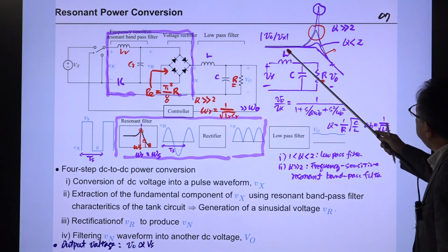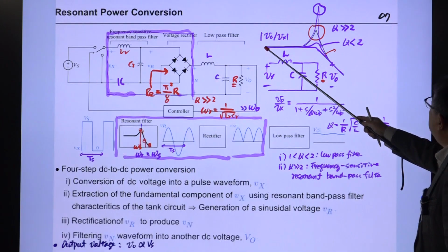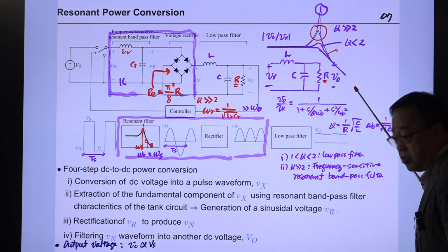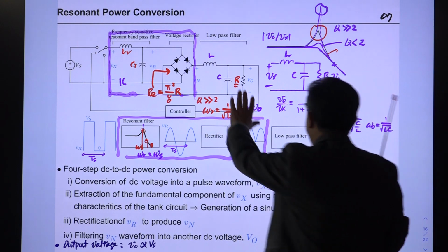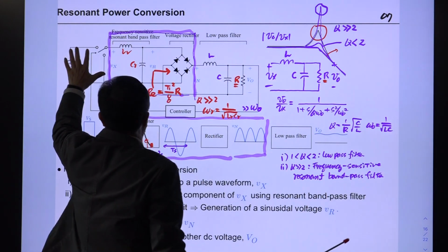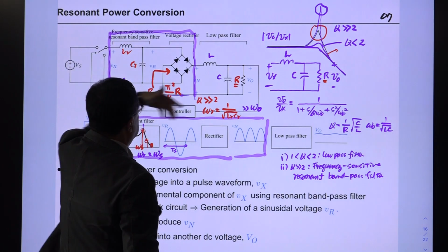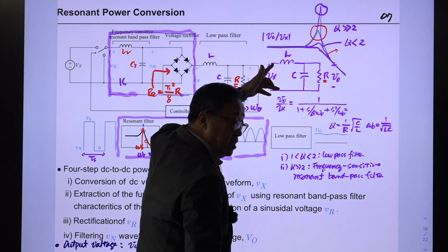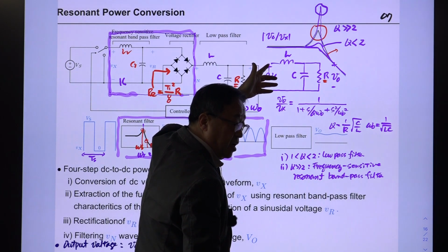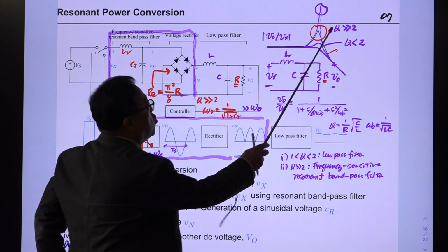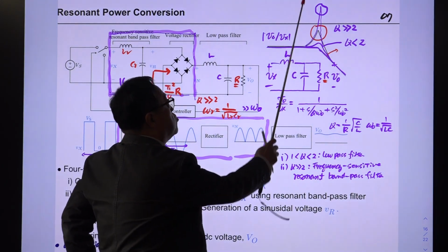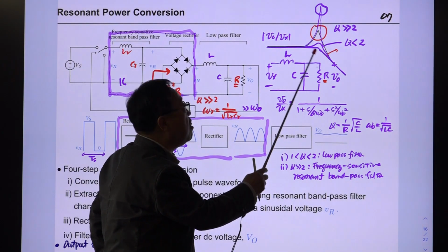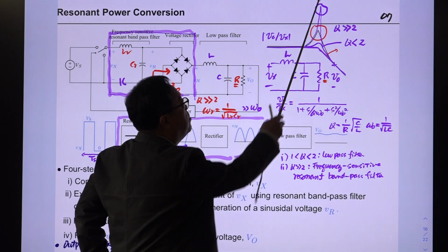With small Q, the frequency response of this low pass filter is something like this. So it only passes the low frequency components of the spectrum of the incoming waveform. So it is a low pass filter. But if Q is increased, the Q produces peaking at the resonant frequency. With large Q, this can be very high.